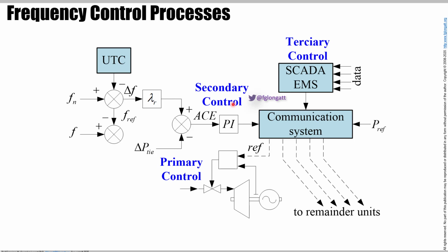The secondary control is slower than the primary control. Time scale of several seconds. It could be even a few minutes, and typically it is a wide area system, okay? It's related with very low speed and is spread across the system, because basically what it's doing is sending reference signals to the primary control in order to recover the frequency. And then we have a tertiary control, which is basically slow and with some characteristics related with economics, okay? I will not go into that detail.